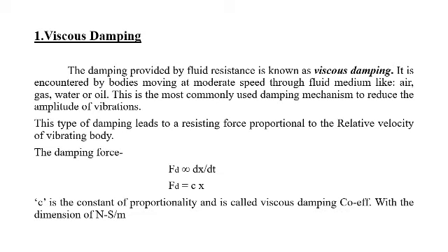First is viscous damping. The damping provided by fluid resistance is known as viscous damping. It is encountered by bodies moving at a moderate speed through fluid media like air, gas, water or oil. In this, viscous damping is provided by any kind of fluid media. This is the most commonly used damping mechanism to reduce the amplitude of vibration.